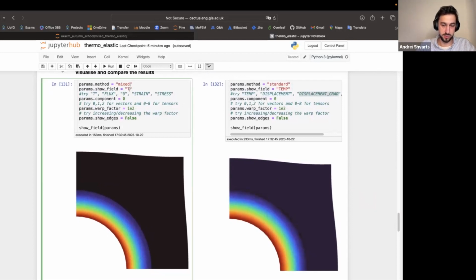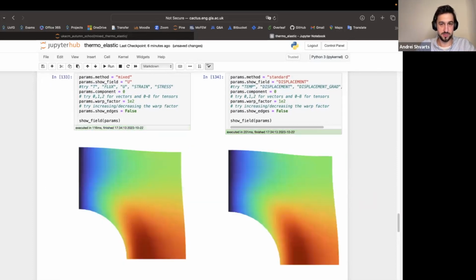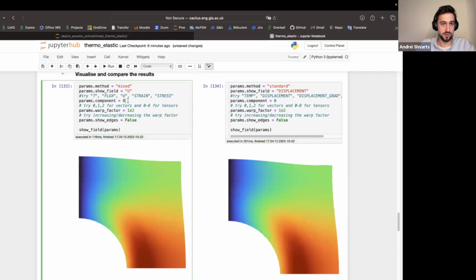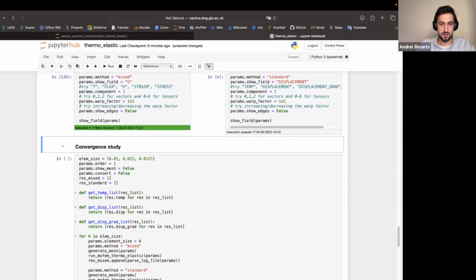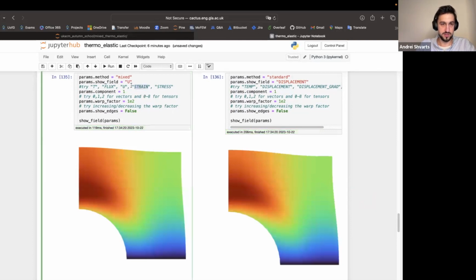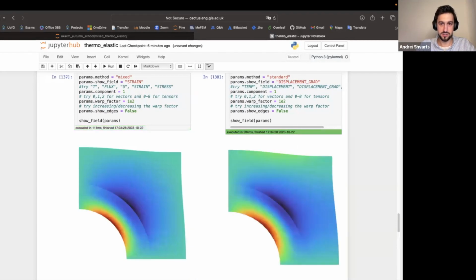If you're interested, you can look into the other fields, like the displacement field. Like I said, displacement is vectorial, so you can look into the different components. So we're looking at X right now. Now we're switching to Y. You can look even into the strain field, and then you have to choose the displacement gradient name over here. So, okay, that's probably the XY term.